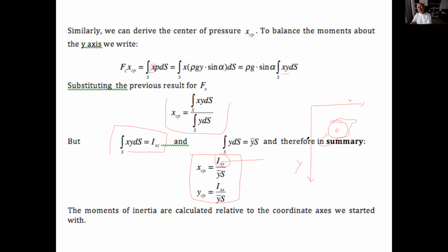It's very much like you spinning. Right now we're spinning it here. So if I spin a circle, an exactly good surface, let's think about spinning something about this axis. If we're spinning it, then there's not going to be side force. But if this is not balanced properly, like it has all kinds of shapes to the side, then I'm going to have, due to the rotation about the x-axis, forces to the side. That is the reason for the mixed Ixy in dynamics. In our case, it is going to shift the center of pressure sideways. That's all.